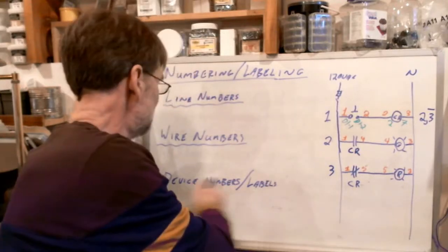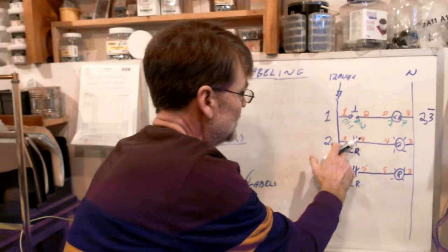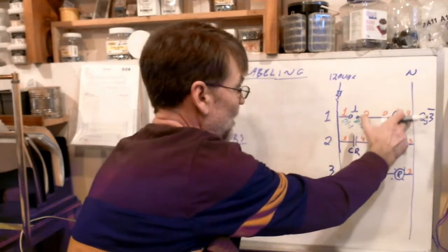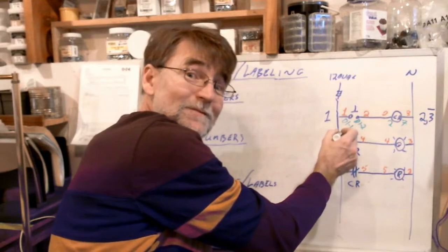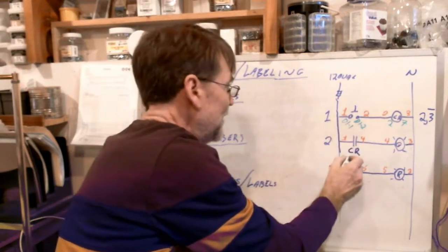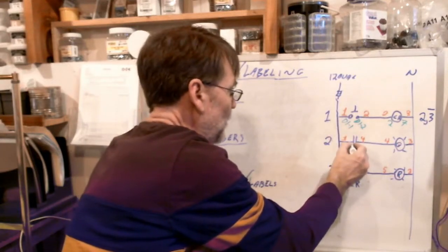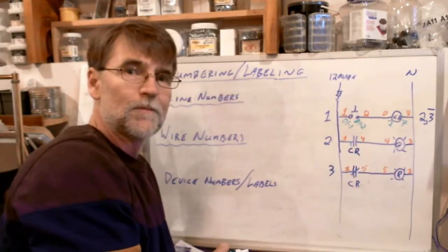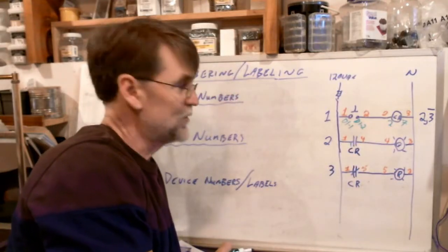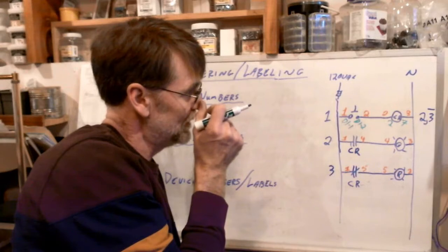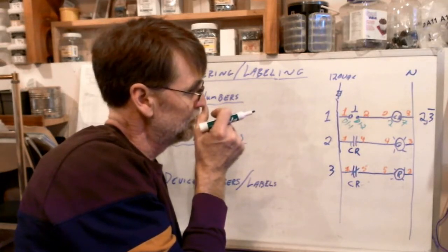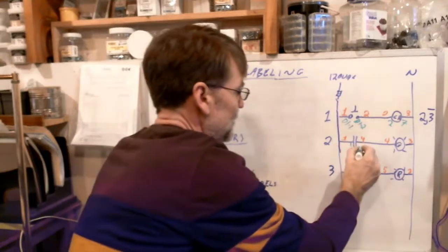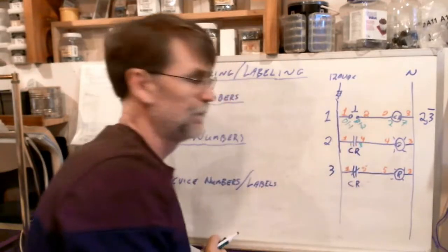So just to finish the device numbering, if this normally open contact is part of this cube relay, the pin numbers are, I'm going to ask you to test your memory a little bit more. So pin 1 would be one of the commons. And this is what I always struggle with. Let me see, can I get this right? I think 3 is the normally open.